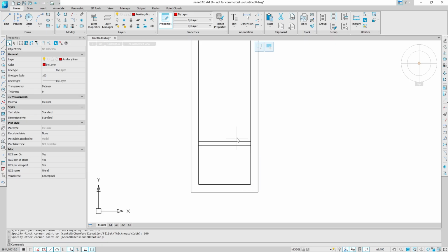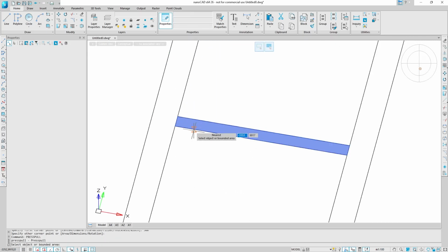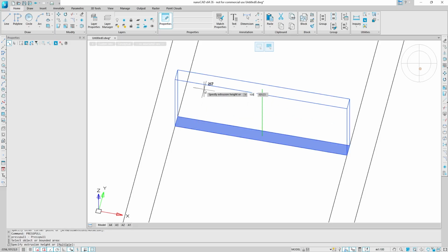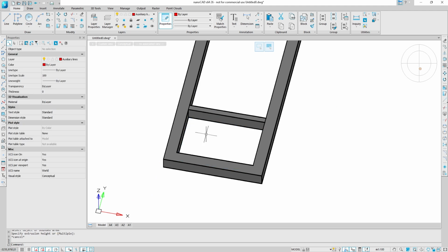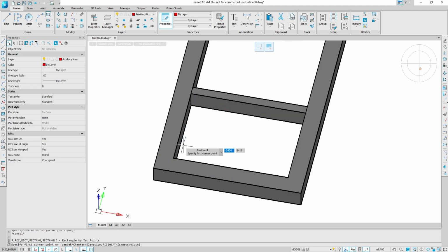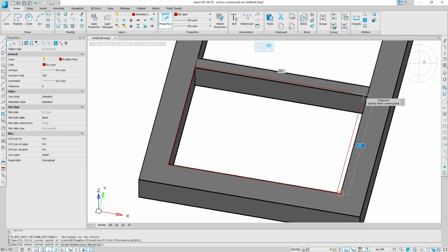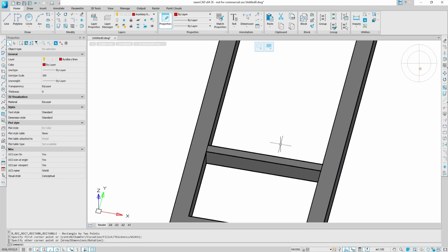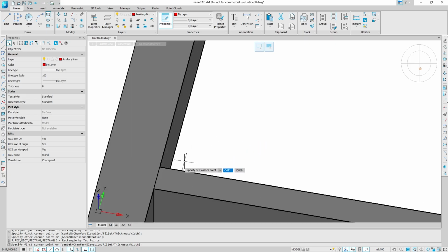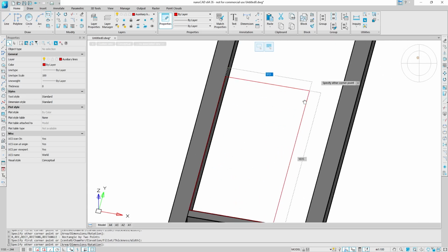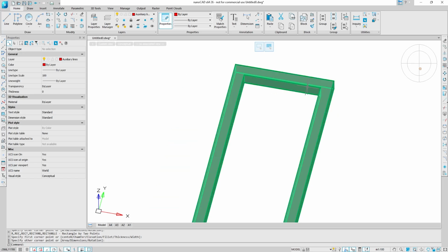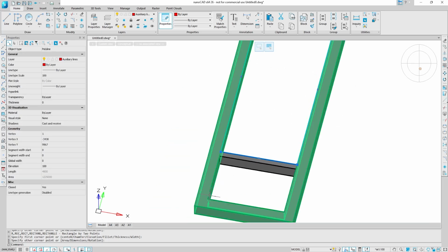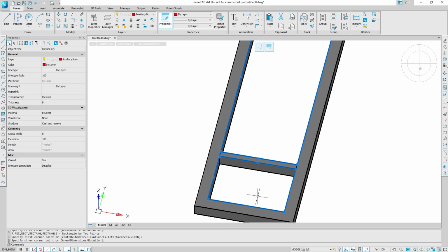Squeeze out constructed contours to a thickness of 100 millimeters using the press pull command. In the upper and lower parts of the window, draw a rectangle for future glasses. The lower one is 500 millimeters by 700 millimeters. The upper rectangle is 700 millimeters by 1750 millimeters. Select the drawn rectangles and squeeze them out by 5 millimeters using the extrude tool.